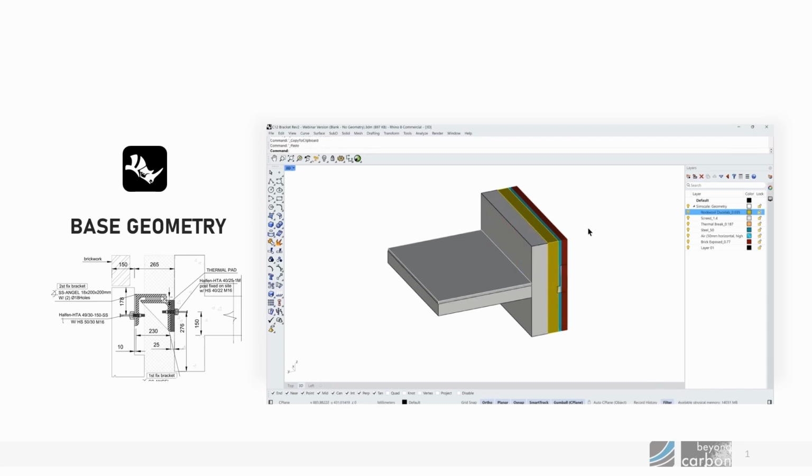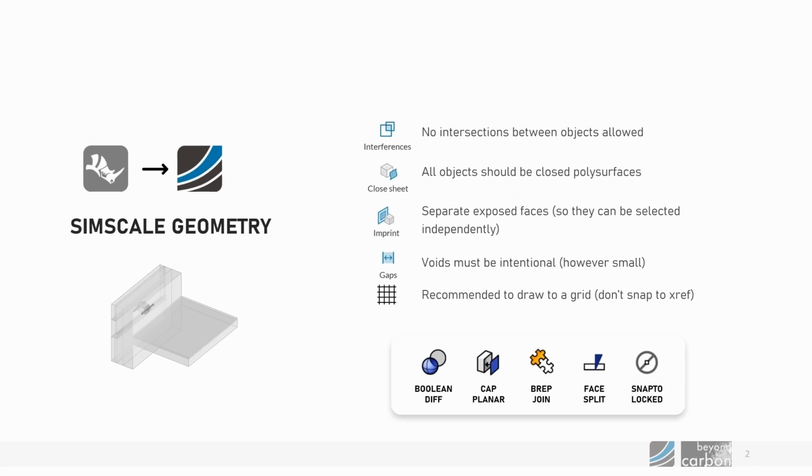This is really important because SimScale has some rules and guidelines as to what kind of geometry it accepts on the platform. Some of the rules to keep in mind are that objects accepted on the SimScale platform are closed solid polysurfaces, which means the ends should be capped and there should be no left behind lines, curves and surfaces. And all the objects are also distinct. There should be no overlaps and intersections between the objects. And similarly, there should be no gaps and voids between the objects unless it's a part of the design. To prevent this from happening, it's good to draw to a grid and snap to object in Rhino.